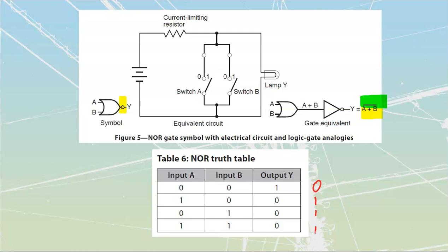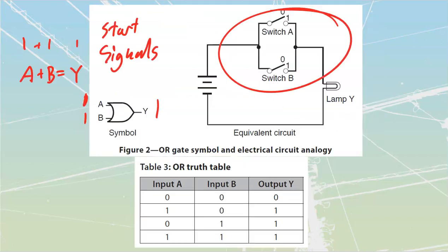Once again, the reason for this is actually that NAND and NOR gates are easier to create than AND and OR gates. So they're more of a base type of gate. So we'll use them. And in some cases, just the Boolean algebra makes more sense to utilize these. Really, because NAND and NOR gates are easier to create, for me to create and use AND or OR gates, these two over here, results in a greater propagation delay.